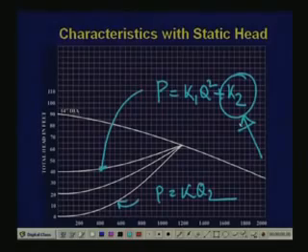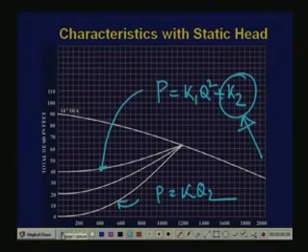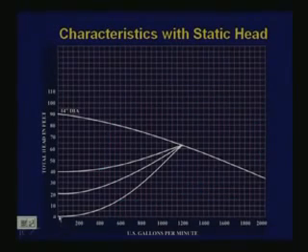Sometimes the pump may be elevated. In such a case, the pump may be below and the load may be at a vertical height. So even if there is no flow, there is always a constant pressure on the pump. For driving such loads, as we shall see, the energy saving is reduced.